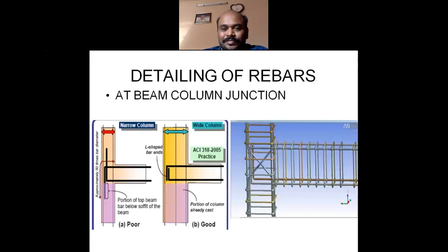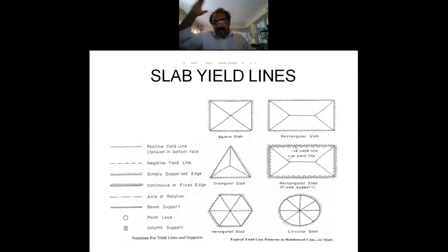Okay. So after that, we come to the slab. In design we start from the slab, and in construction we start from the bottom. So the topmost portion is the slabs. Assume a Britannia 50-50 biscuit, a square shape. You apply force on it, in slow motion, and it will crack. If you uniformly apply the force, it will crack like triangles. That means the load is transferring like this. You take a Britannia milk bikkies, apply a force on it in a uniform manner, and it will crack like this. This line is called a yield line.